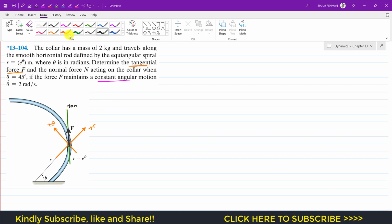Now, as we know, the angle between the tangent and the radial direction is always that psi angle, and similarly we need to determine the normal force N. So the normal force is going to be perpendicular to the tangent. Let's say that this horizontal rod is applying the force on this collar in this direction.